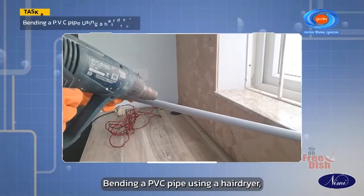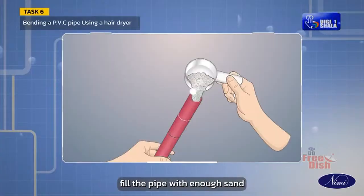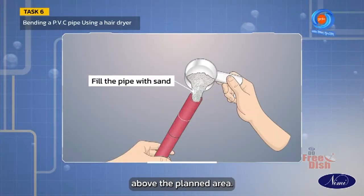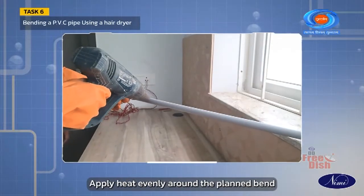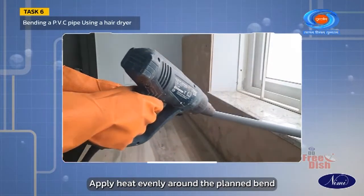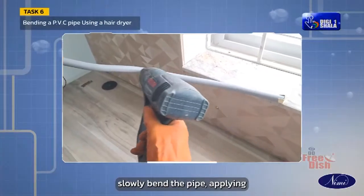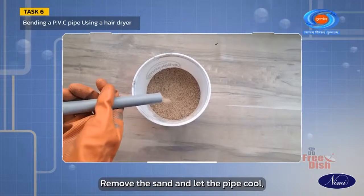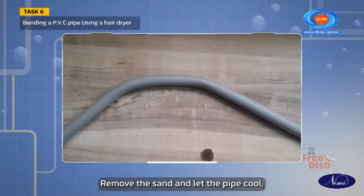Bending a PVC pipe using a hair dryer. Fill the pipe with enough sand to cover 2 or 3 inches above the planned area. Apply heat evenly around the planned bend. Slowly bend the pipe, applying more heat as necessary. Remove the sand and let the pipe cool.